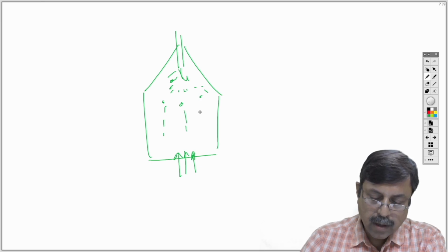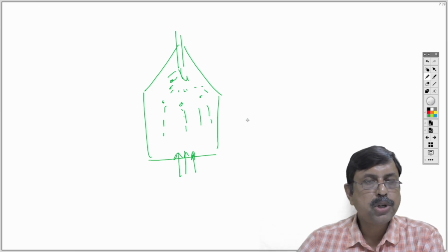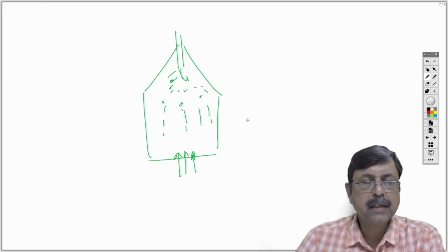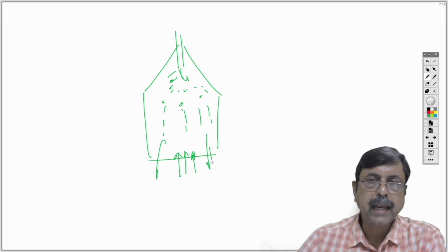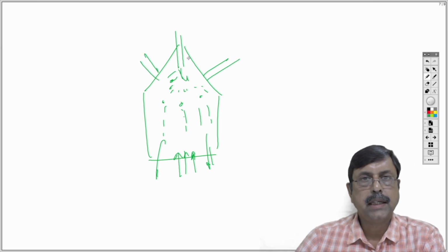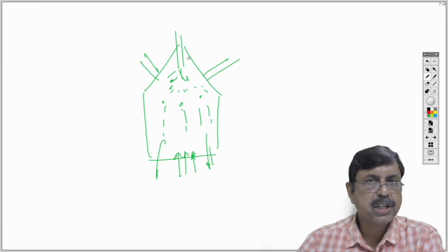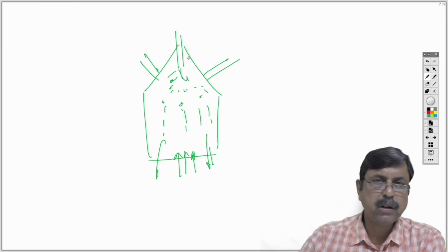It will come down, and while it comes down it will come in contact with this gas, and thereby the liquid portion of those droplets will be evaporated and only the solid portion will remain, which will form some solid particle or some porous particle. All the solids will be collected from this end. The gas will be thrown out from the other end. So that's how the spray dryer works. The configuration of spray dryer will be a bit different from application to application, but overall idea is the same.